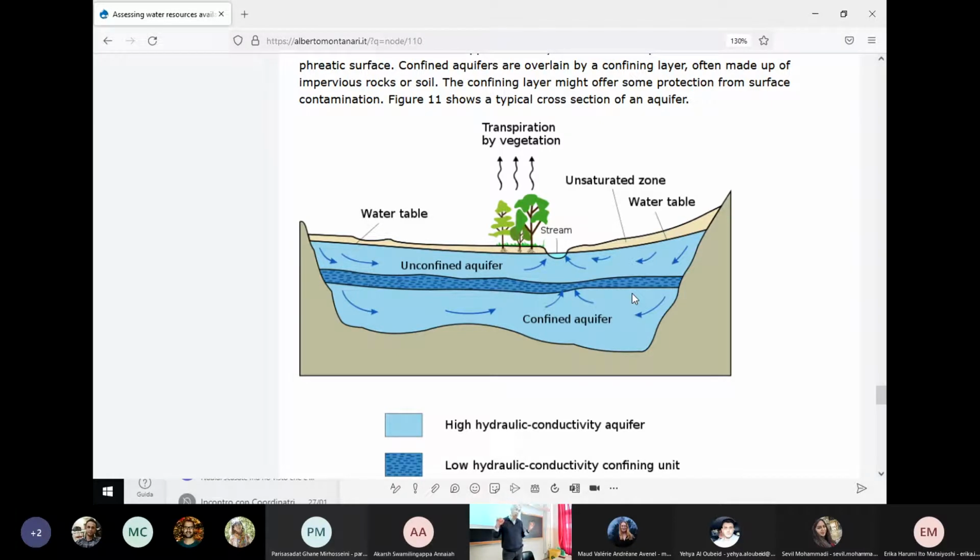And multi-windows means that we establish an artificial connection between aquifers, because the well is like a pipe with several holes, and therefore increases the permeability. Several holes, several windows, increase the permeability artificially. And we don't know to what extent this helps in recharging the unconfined aquifer. It's something that we simply don't model because we don't have enough information to understand how water travels between aquifers.